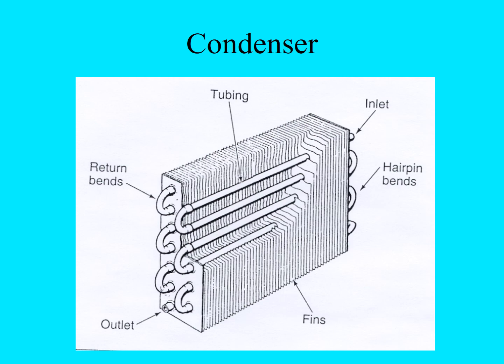So the cooling fins, most of these are made out of aluminum. The cooling fins have to allow air to flow through them. And some of the problems that we have with condensers, where they're right in front of the vehicle radiator, is that they collect a lot of debris. So sometimes the cooling fins will get clogged up with fine dirt, road debris, paper bags, plastic bags could get in front of the condenser.